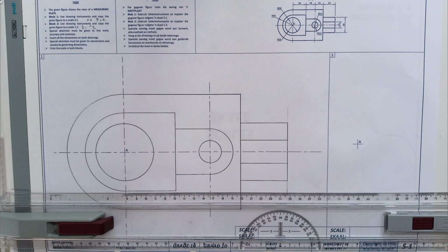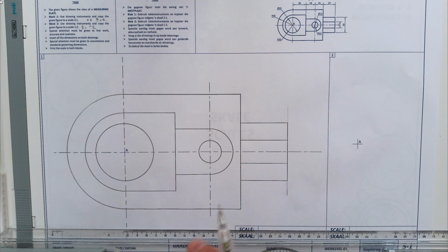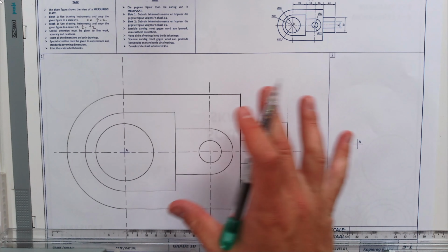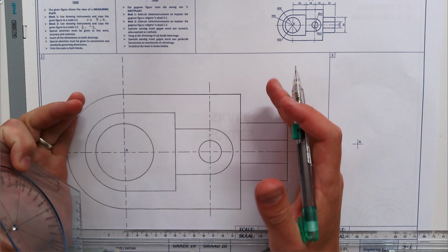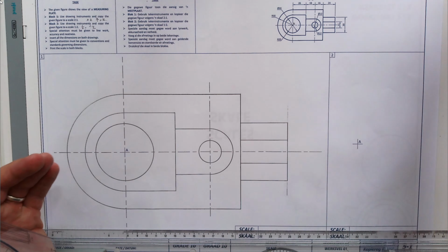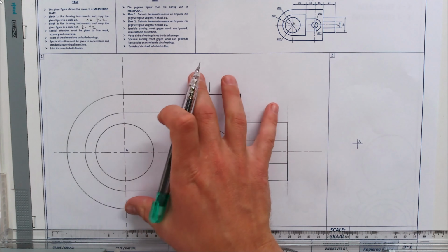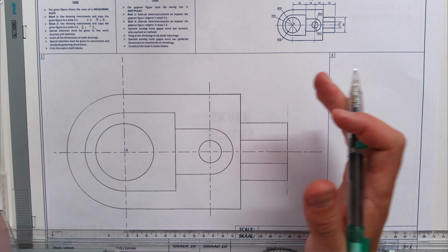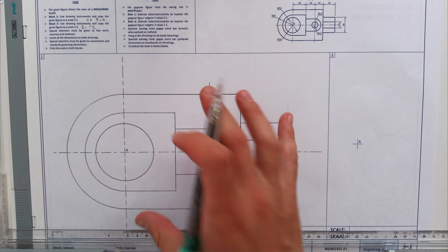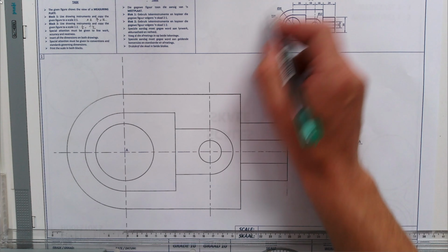Now, although this is a scale of 2 to 1, we're still going to give the actual dimensions. The only thing that is happening with a scale is the scale is used to make the object bigger. We do this to make smaller objects appear bigger on paper for detail. Because at the end of the day, the person who is going to make this product needs to have its actual dimensions. We only make the sketch larger so that the person can see more detail. But we still keep the dimensions as the original dimensions as seen over here.